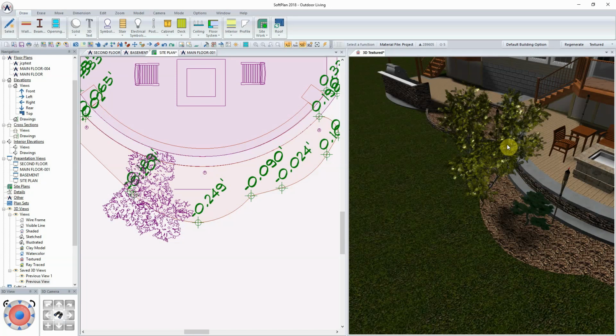And so these types of symbols have a lot more detail to them, a lot more surface count, and can slow down your model. However, the depth value that you get from them is unparalleled. And so what you'll really want to do here is, in a lot of cases, I will use billboard type trees in the background, and then I will use these high surface count trees in the foreground.